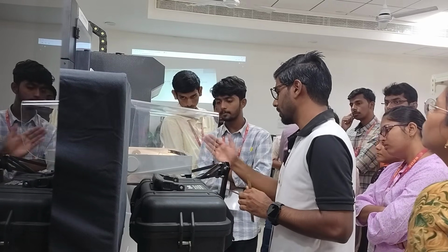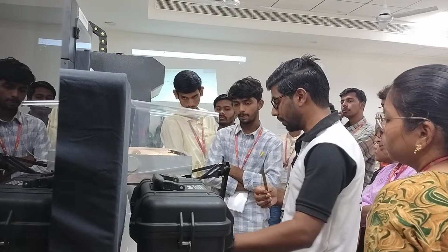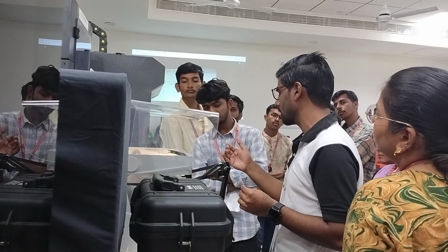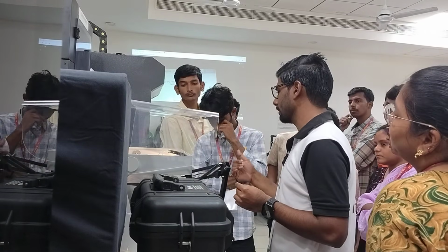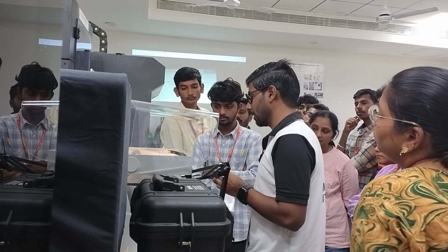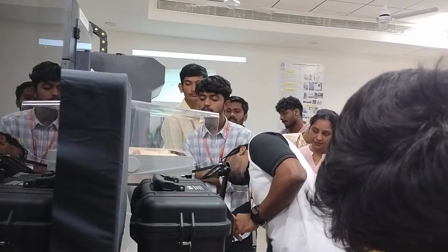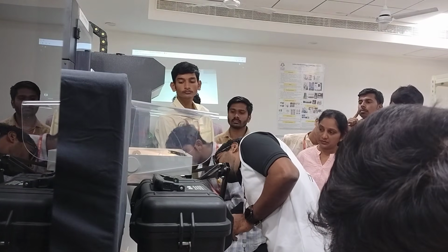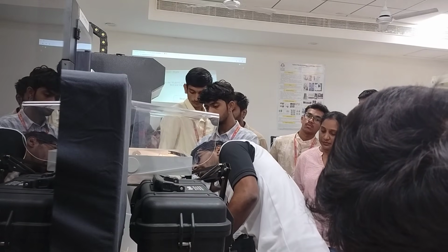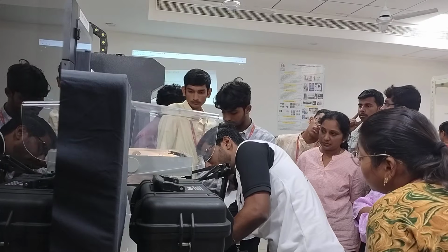It is moving to the right position. It has moved. Now it is telling me to place the plastic shim between the print bed and the plastic nozzle. As I showed you before, there are two nozzles. The front one is the fiber nozzle. The second one is the matrix or the plastic nozzle. So I'll have to place it between the plastic nozzle and my bed. I have placed it there, and then I click next.